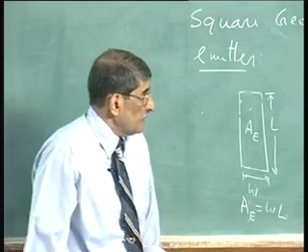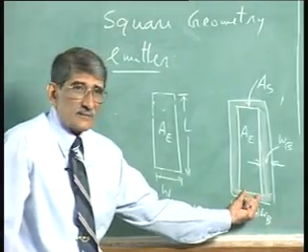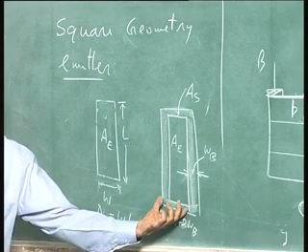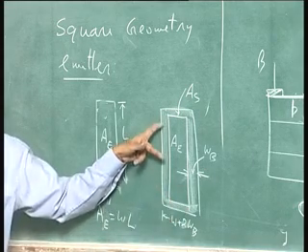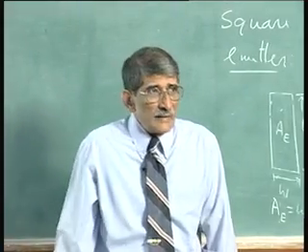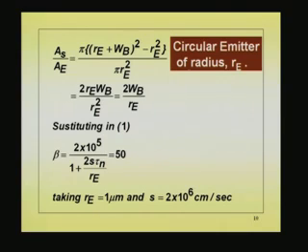So, it would matter quite a bit when the length and width become smaller and smaller, and they have made devices which are large, W quite large and also length large. There the beta approaches closer and closer to what they have estimated. Now, you cannot say go ahead, make the device area big so that you can get rid of the surface effect, because if I make AE larger here, that effect goes off. If you take a device which is 1 centimeter square area, perfect, beta is 2000, you will get.